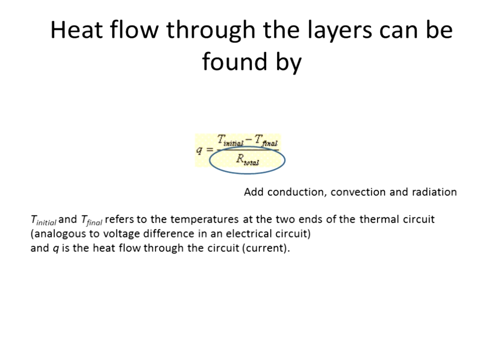So then, what do we do with that information? Well, the total heat conduction then would be the temperature difference divided by that total resistance that you added, okay? And then you have your initial and final temperatures, okay? And that is how you calculate.